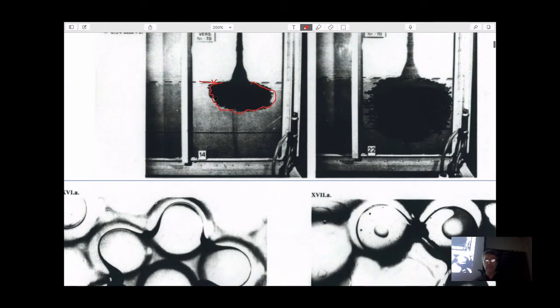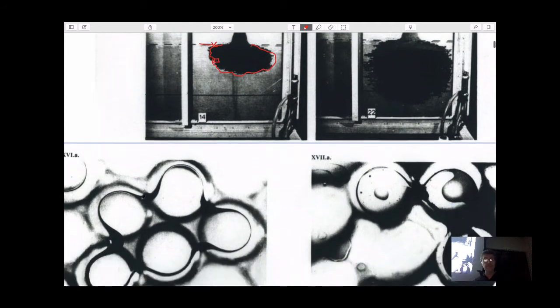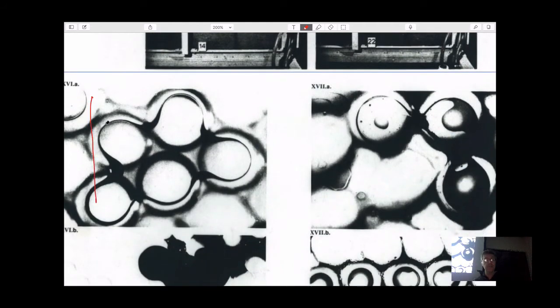If you zoom in on portions of this and look at exactly what a portion might look like if you blow it up, then you find out that the water is present around the particles as a monolayer because it has an affinity to quartz, water wet, and that any contaminants that get in there will rest in some little pockets which look like this. And so understanding the mechanisms by which this happens is the key to understanding what's going on.